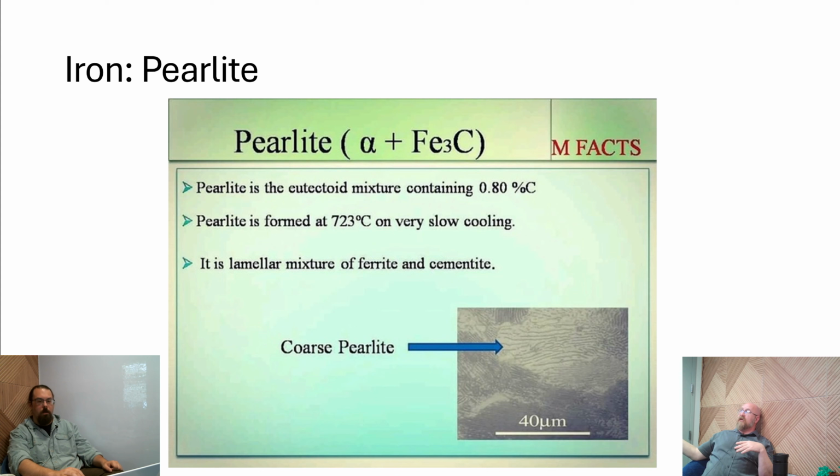This will make a lot more sense once we cover cementite. So hit the next slide. Just real quick, I want to point out one thing where it says coarse here. When we're talking about coarse perlite, it's the distance between the layers. There's a region in the lower right here that's a finer structure, but this area here is also still perlite, because it's still forming those lines.